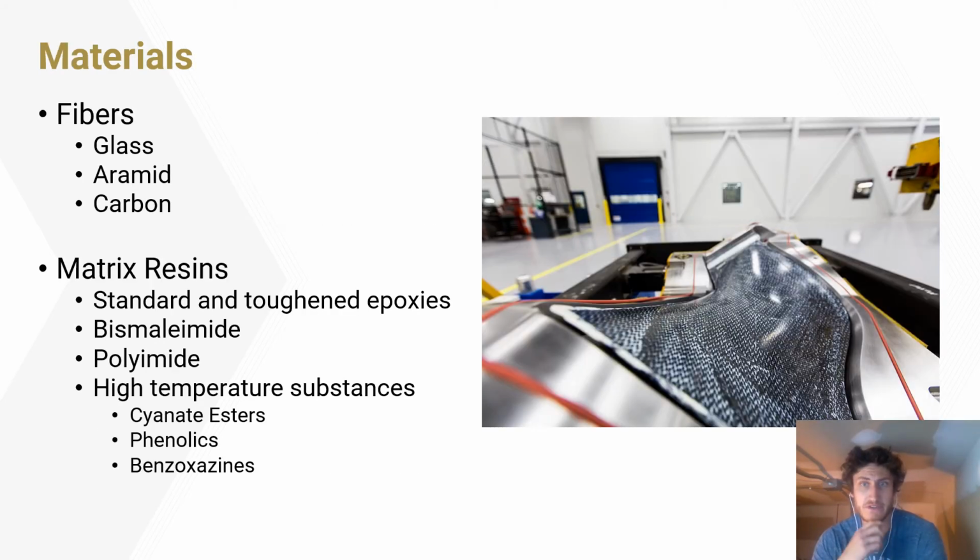So when it comes to materials used in aircraft engines, they use pretty much the variety of materials seen across the board. So fibers, you're going to see use of glass, aramid, and carbon in various applications. Glass is often used in the acoustic panels and nacelle casings and in all the cowlings. Aramids can be used in fan containment cases and often in parts of the fans themselves. But carbon fiber, especially high-strength carbon fiber, comprises about 94% of the over 12,000 metric tons used in market and is going to be the primary fiber used for the next decade in all looking forward forecasts.